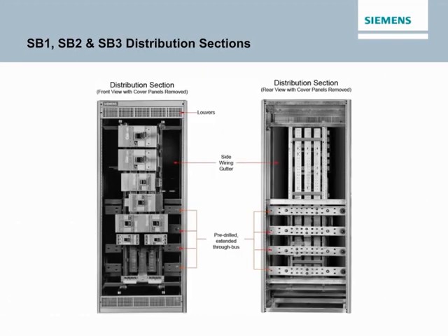SP1, SP2, and SP3 distribution sections are constructed with generous top and bottom gutters. In cable entrance sections, no obstruction is less than 8 inches above the floor, and no live bus bars are located less than 10 inches off the floor, so there's plenty of room to run cables into a distribution section. Standard bolted gutter covers give complete access to load conductors. Hinged gutter covers can be furnished where quick access to load conductors is desired.